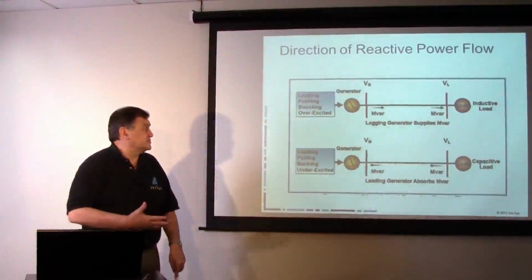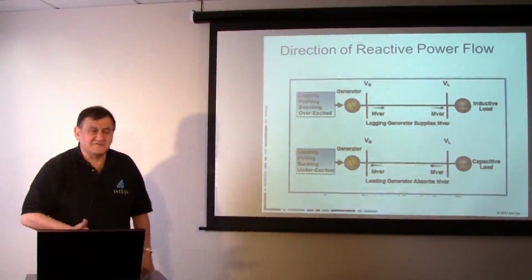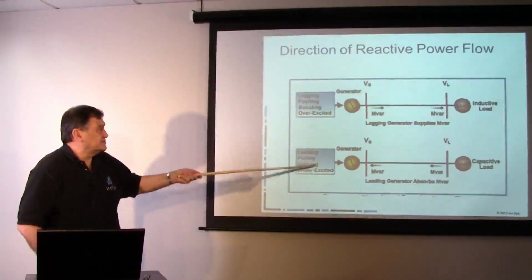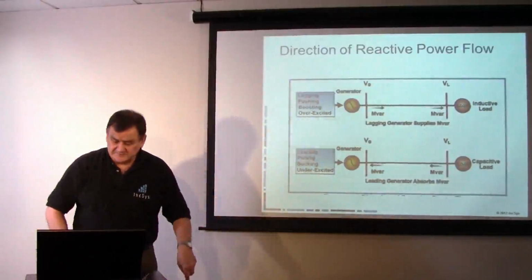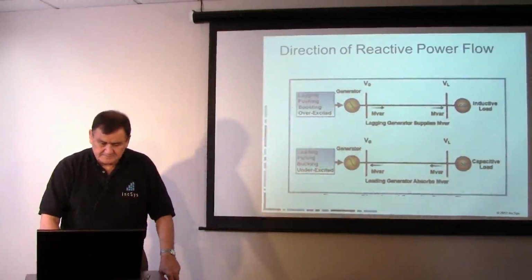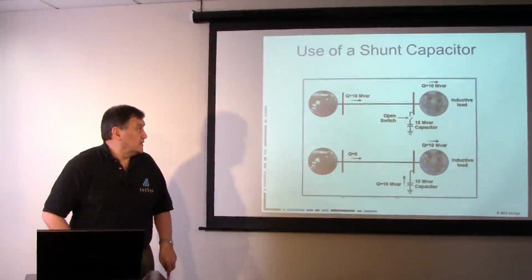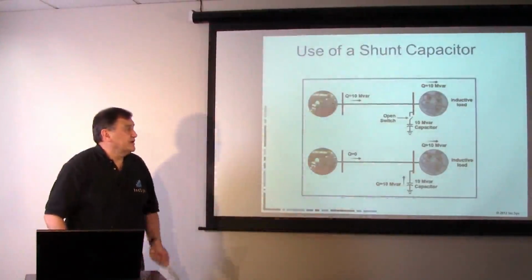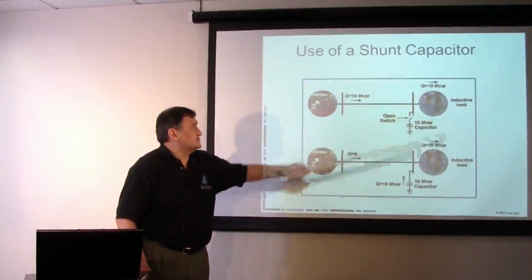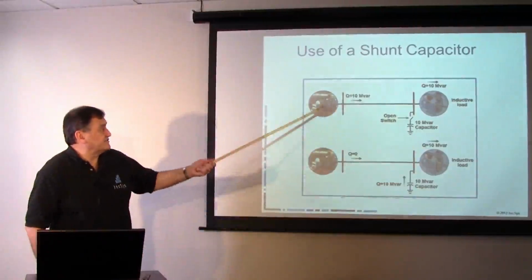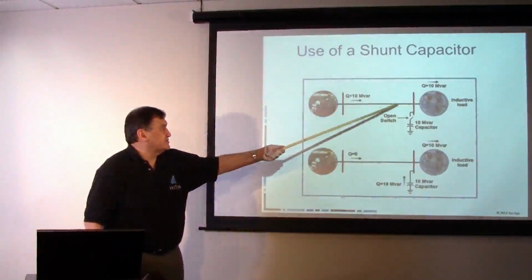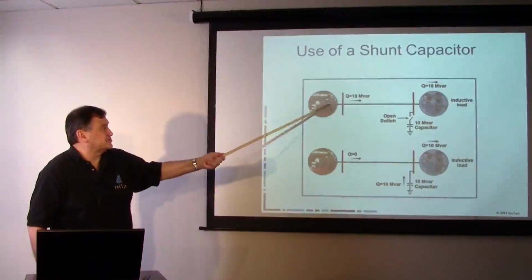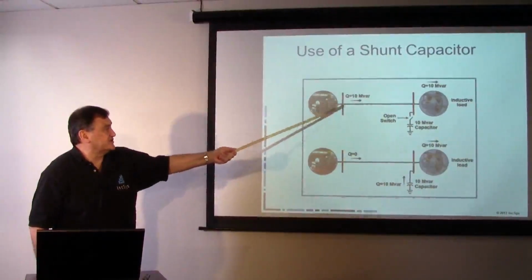And again, for those preparing for the NERC test, you'll often get questions that ask you to understand which of these modes are applicable for different situations. Now, in general, we have generators and we have loads which are inductive. So here we have 10 megavars coming out of this generation, pushing megavars onto the system. It's overexcited, it's working in a lagging mode, and it's boosting voltage.